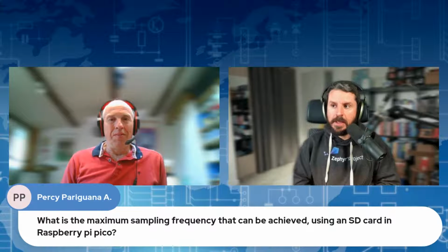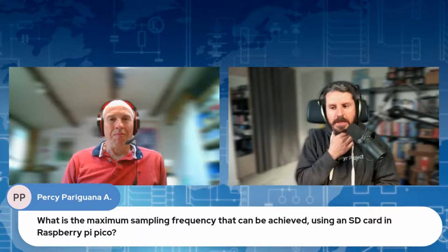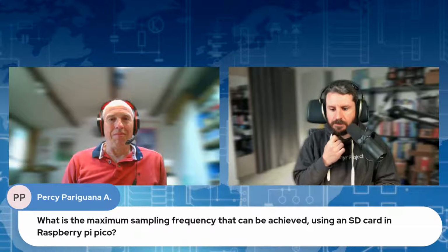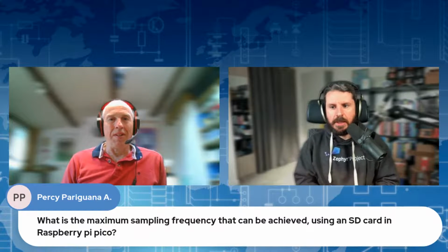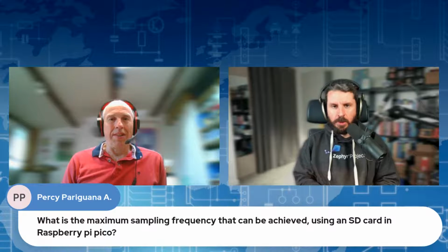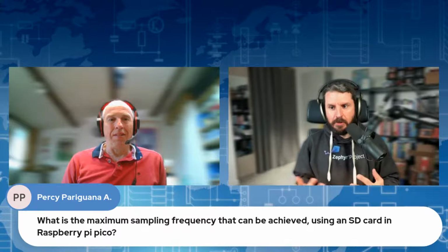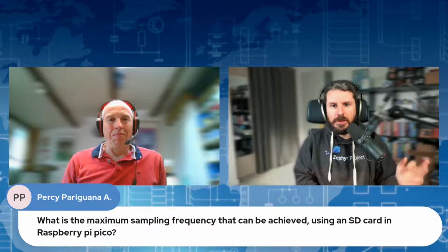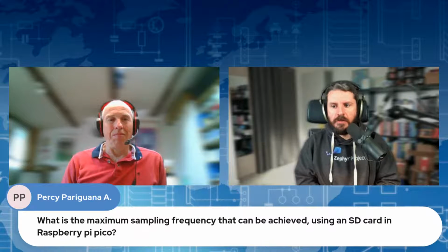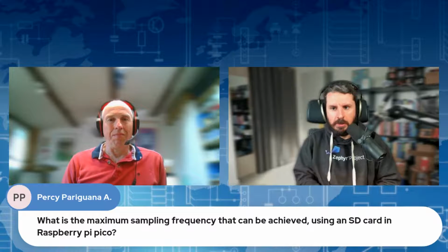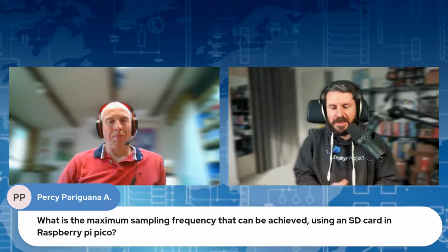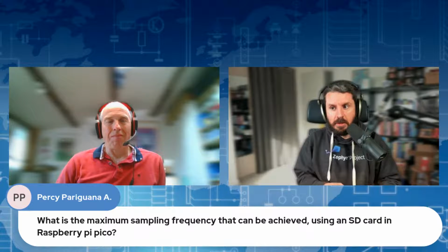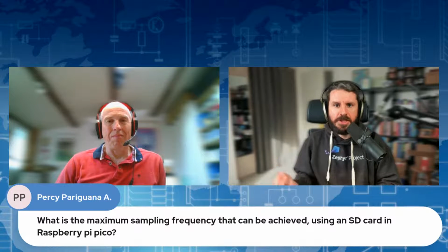There are two more aspects to the answer. For many sensor drivers, one interesting thing is that there's also support for the so-called trigger mode. For an accelerometer, many sensors support, rather than you having to sample quite aggressively to figure out a spike in acceleration, like to detect that your device was dropped on the floor, you can instead tell the sensor that you'd rather get an interrupt when a particular threshold is crossed.